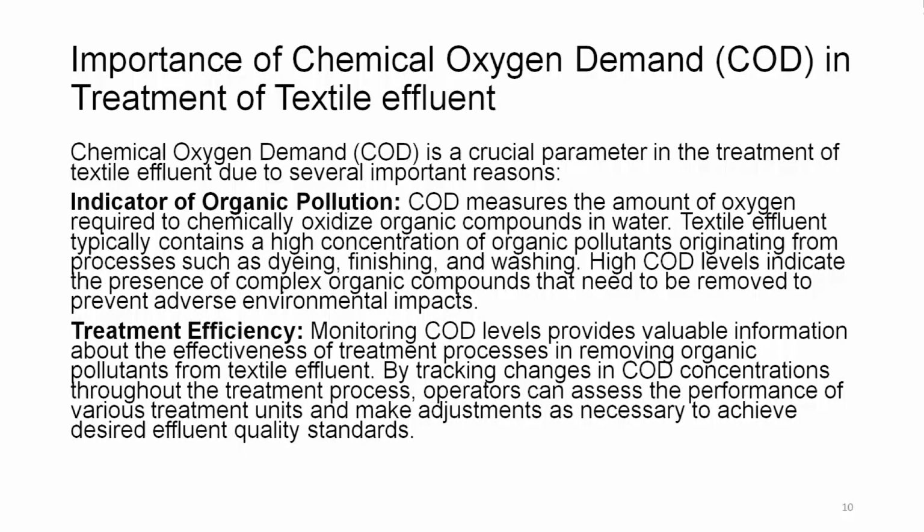Moving on, let us see what is the importance of COD in the treatment of textile effluent. COD, or chemical oxygen demand, is a crucial parameter in the treatment of textile effluent due to several important reasons. Indicator of organic pollution. COD measures the amount of oxygen required to chemically oxidize organic compounds in water.